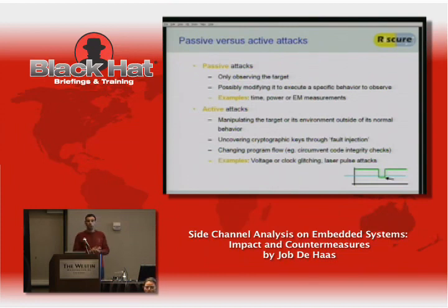And it might be simple faults like, okay, this is a decision point and I want to throw the switch to a different decision. But it may also be in crypto operations. And you can show that in a lot of crypto operations, if you have it running with the correct key and then induce a fault, from the differences in the crypto results with the same input, you can deduce information about the internal key. So there are a lot of attacks possible with these fault injections, and it's a very powerful technique. But we'll focus on the passive attacks for today, and look at what you can do when you look at power or electromagnetic field.